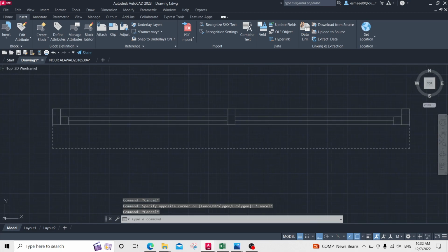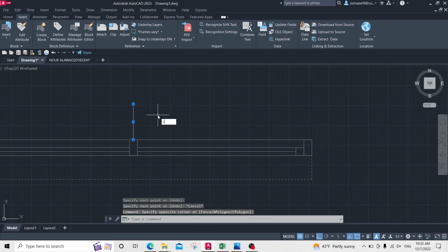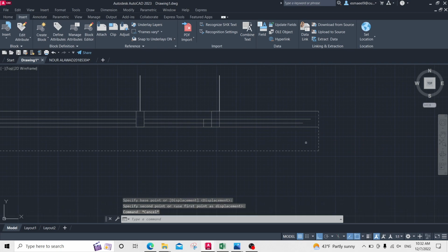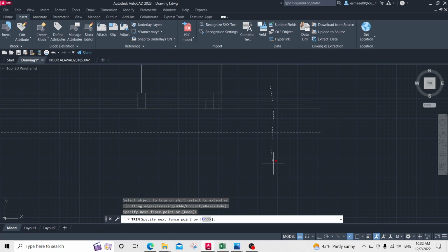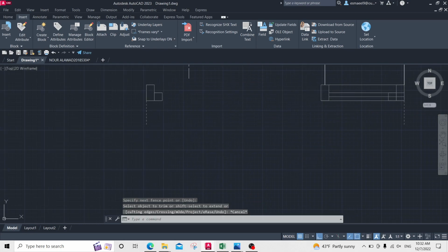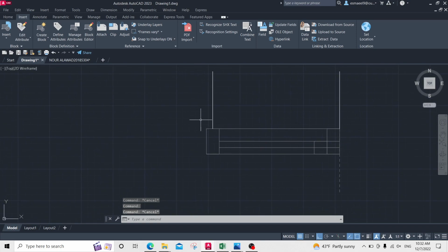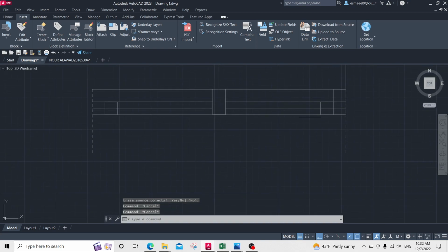From this line, CO 50, bring these lines, move until this point, even this line, move until this point, and now TR for everything, and TR for these lines, delete the others, select this line, these lines, and then mirror, MI, click no, and click line.